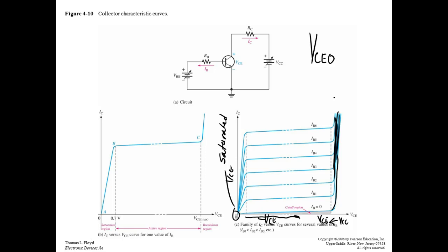So what we'd have to do is know the cutoff voltage, which might be somewhere in here. The cutoff voltage is going to be below the breakover voltage. And then the saturation, where it saturates at. And then we can draw a line between that. If we're going to operate it in the active region, we would try to bias it in the center. And then I can apply an AC current to it, and we can figure out exactly what's going to happen to this guy down here. It's really, really neat.